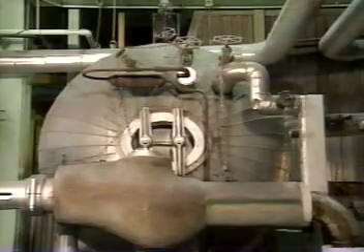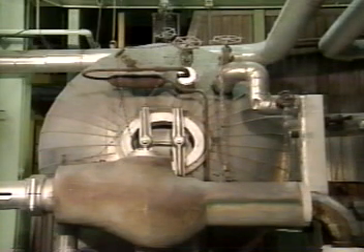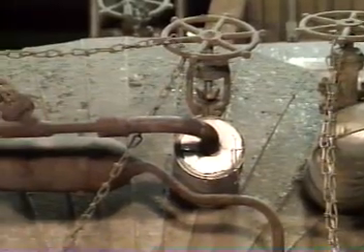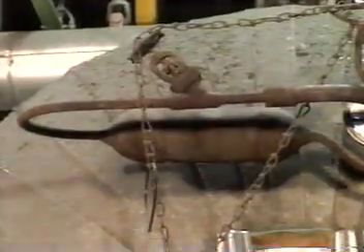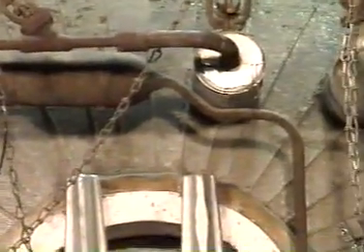When pressurized vessels contain steam or some other vapor which could condense in the upper low-pressure reference leg, the level indication would again be extremely inaccurate. We would now be sensing the hydrostatic head of the condensed vapor as well as the static vapor pressure on the reference leg. When condensation could be a problem, the upper sensing line is intentionally filled with liquid.